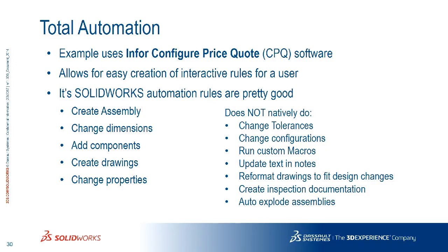So the question was, any preference between VB and C#? I found actually if you're writing macros in SolidWorks using VBA, sometimes they tend to run a lot faster than if you have an external program, VB.NET or C#. Either of those two languages, they seem to compile to the same code. So I really have no preference between VB.NET or C#.